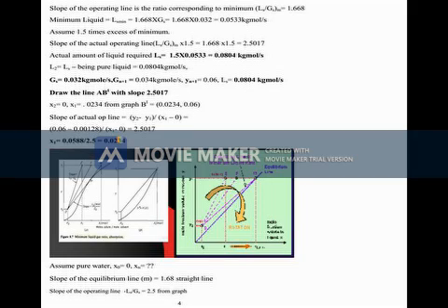Now, I assume some efficiency also. In that case, if 6 is the number of stages without assuming efficiency, and the efficiency is 50%, then 6 will double. 12, there we require 12 plates. So you calculate accordingly. So the design is okay.